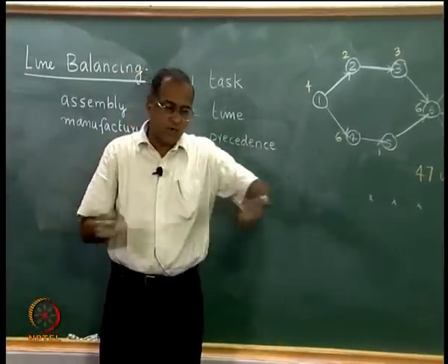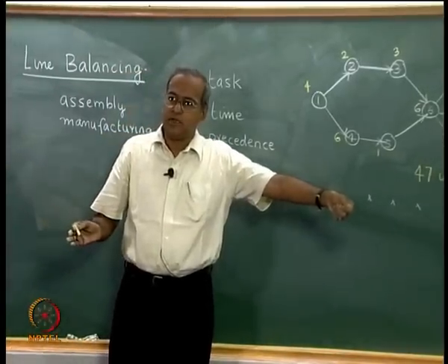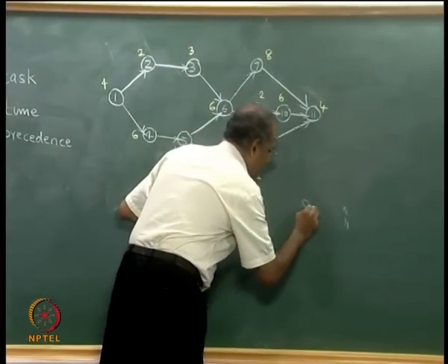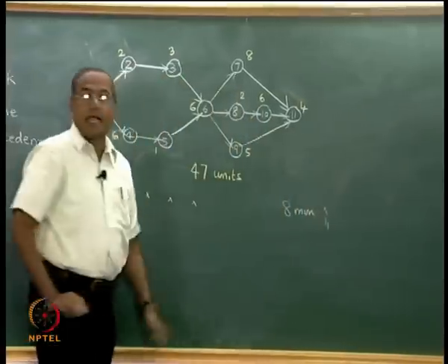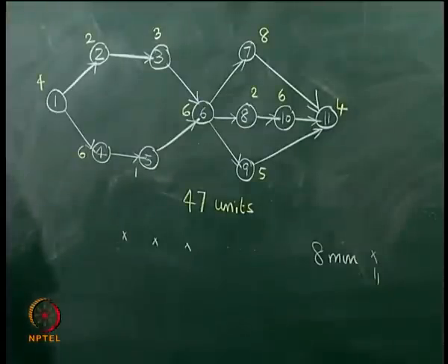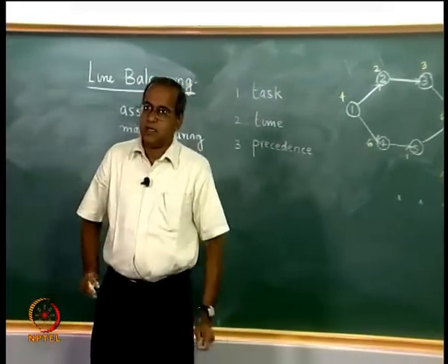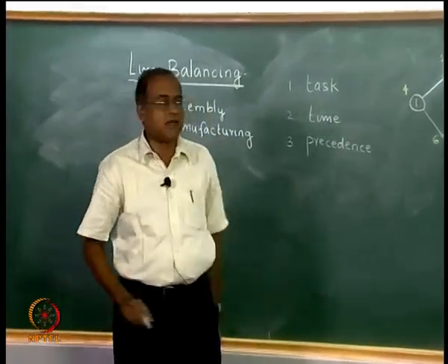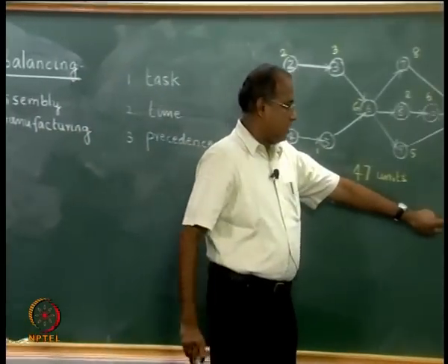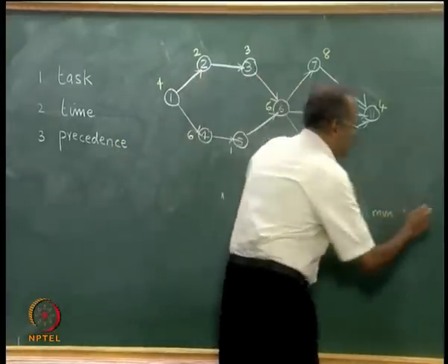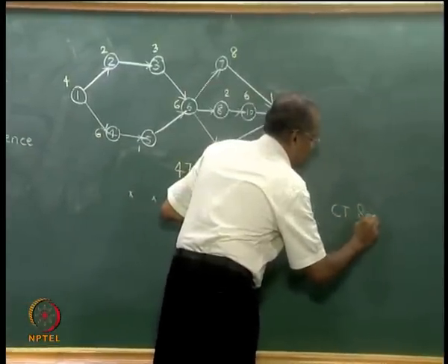So, if we create a situation with 11 workbenches and 1 operator doing each, the output can be 1 in 8 minutes, as long as we do not have parallel workstations. So, with 11 workstations, each carrying out one task, we will have an output every 8 minutes, and that is called the cycle time. So, the cycle time in this case will be 8 minutes.